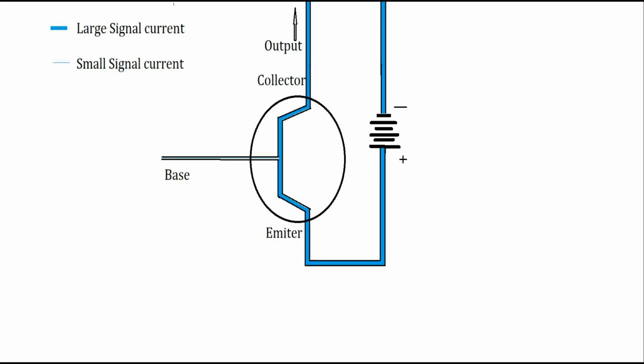So in this circuit, we've connected this PNP transistor emitter to the positive side of the battery. The collector is connected to the negative side of the battery. Now the collector is considered to be the output of the amplifier. So it could feed another amplifier, so you have two amplifiers. It could feed a chain of them. Or it could go into a mixer or into a speaker.